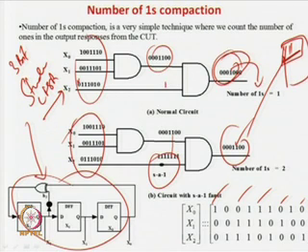If you are using all alternate patterns, then you are in a problem, because you have to run through the whole LFSR and it will take time. And if you are using the same compaction technique with this other sequence of test vectors, then there is a lot of aliasing effect. Then you are at a problem, you have to use the alternative test, and it takes a long time to generate.